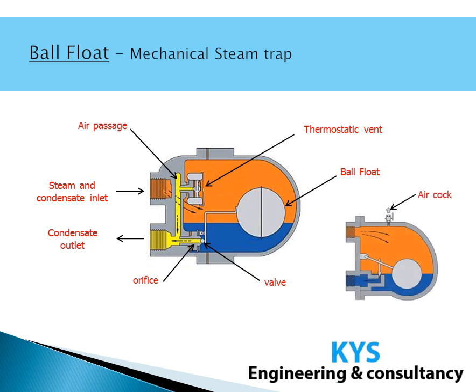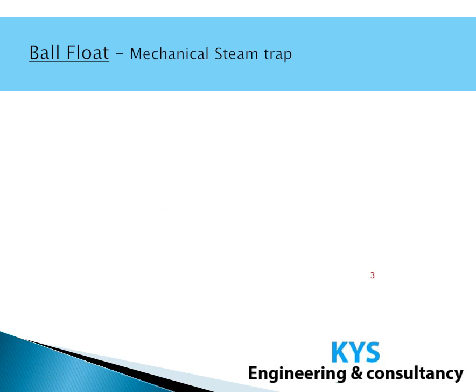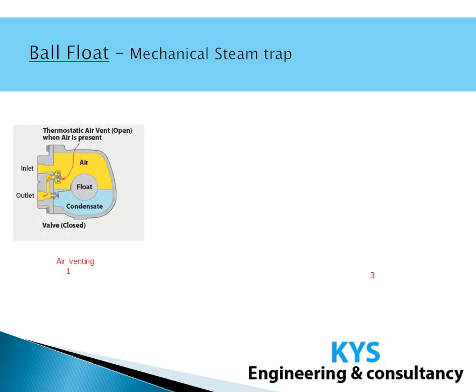In the earlier design, this thermostatic vent was missing, so an additional valve was used which was operated manually to release air and non-condensable gases at startup. Now let us see the operation of the ball float steam trap.